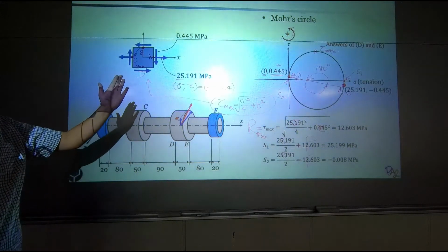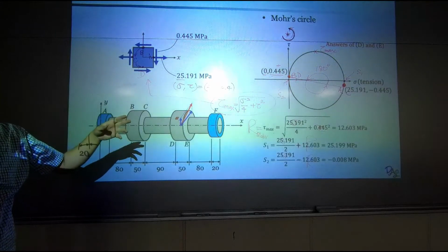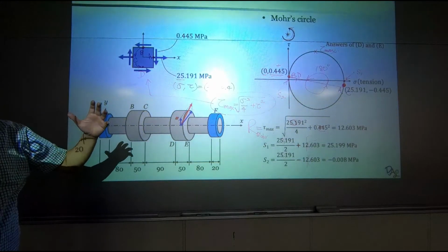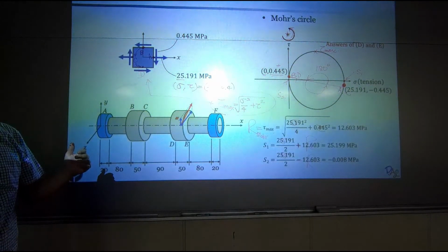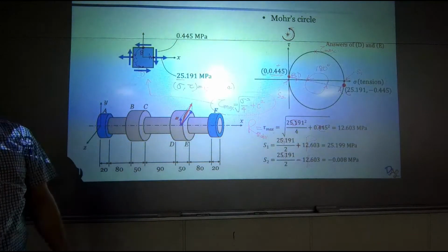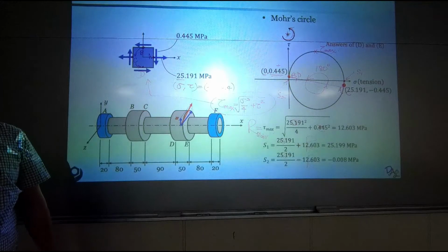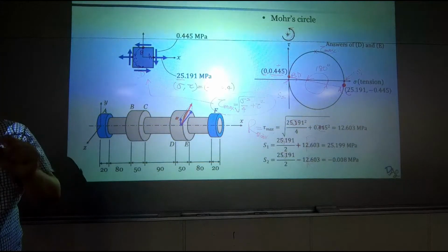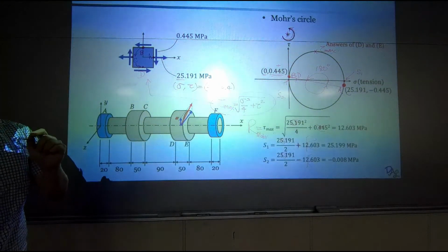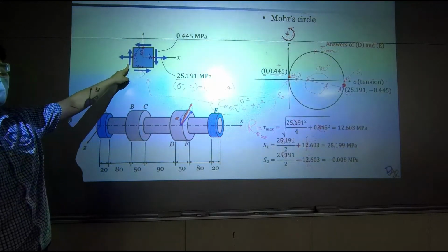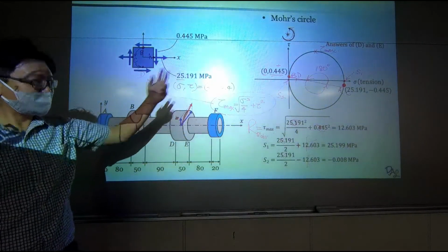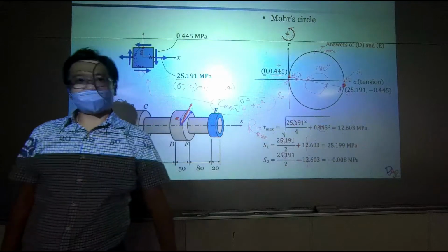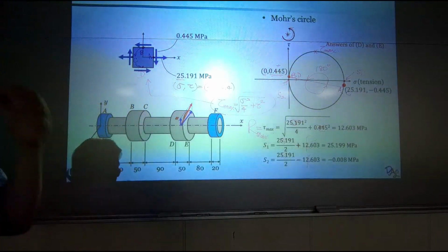Starting from the balance of moment, calculating the reaction forces, draw the shear force diagram, making an integral, draw the moment diagram, figure out which position is having the largest moment, analyze how much normal stress and shear stress this position has, and then plot out the load condition right here, draw the Mohr circle, calculate maximum shear stress, and also first and second principal stresses. That's what you need to do for your exam.